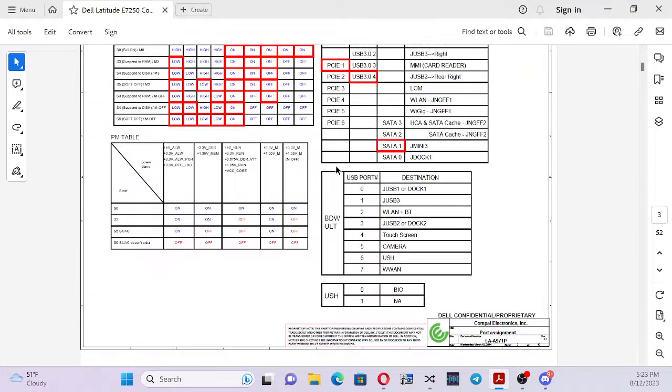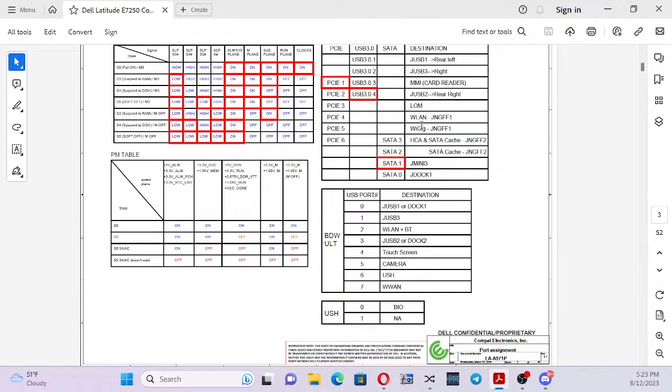This kind of gives you the power states, what's necessary for a computer to switch on. If you're going to be repairing computers, you need to know this. You definitely need to know how to interpret this, how to read it. So for example, this tells you the states. S0, that's when the laptop is functional, when it's on, when it's working. S3, when it's suspended to RAM, it's in sleep but suspended to RAM. S4, it's in sleep but suspended to the hard drive. And then S5, it's in soft off.